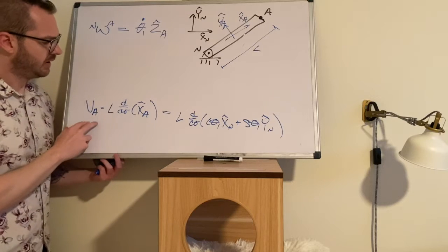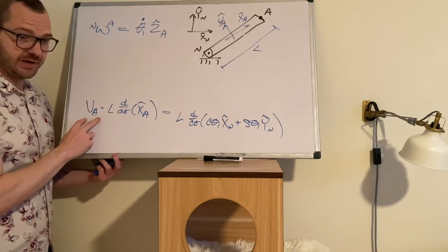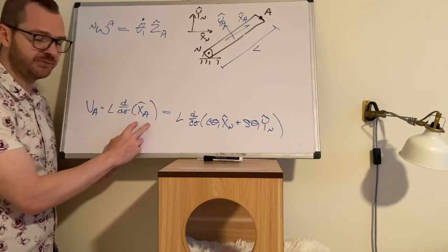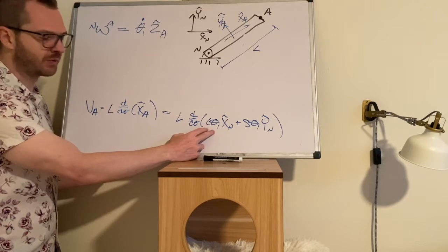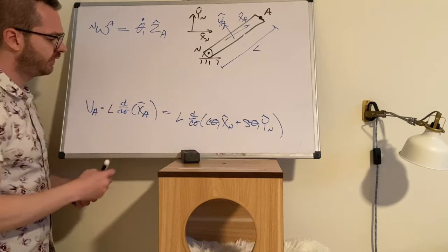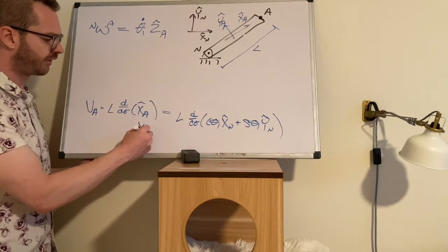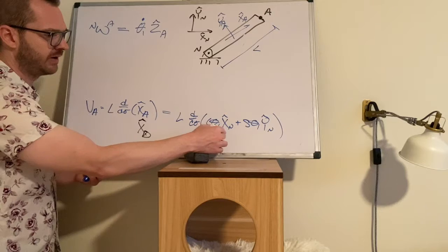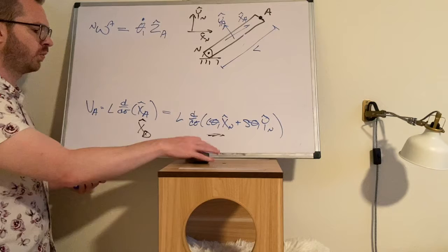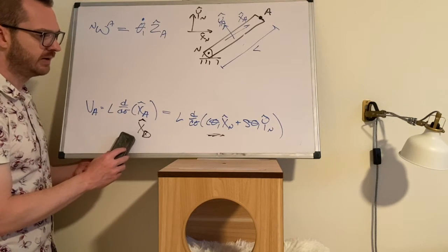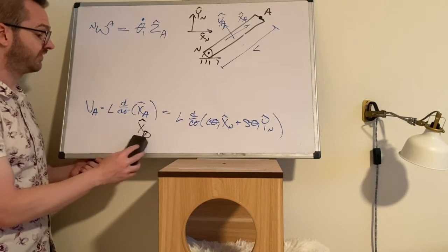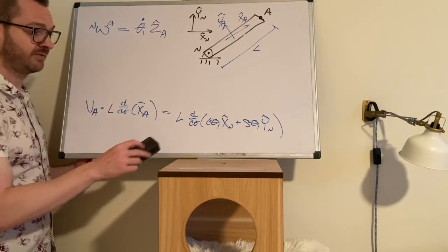So here's where we are. We've taken, this is linear velocity. We're looking at a ddt of a moving frame. I have replaced this moving frame with its definition, and we're going back to the end frame. Quick comment, if you're using relative angles, and this were the D frame, then you'd have to roll this definition all the way back to the end frame. That's one of the reasons why relative angles can get more complicated, but just be aware that in the future we're going to be using transport theorem, and it's going to replace this long process anyway, which is really nice.